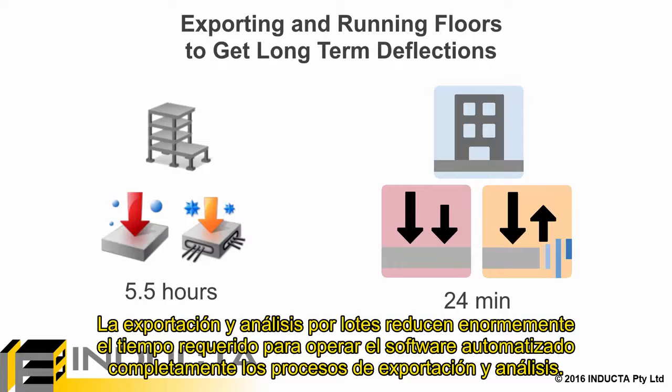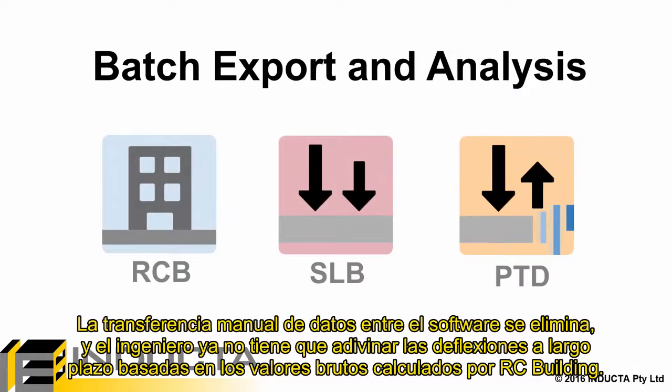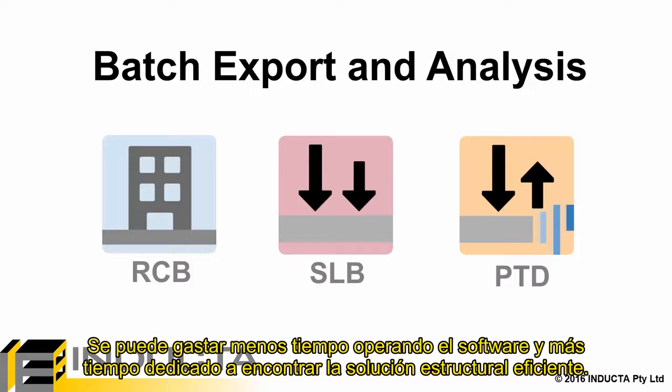The batch export and analysis greatly reduces the time spent operating the software by fully automating the exporting and analysis procedure. Manual transfer of data between the software is eliminated, and the engineer no longer has to guess long-term deflections based off I gross values calculated by RC Building. Less time can be spent operating the software, and more time spent finding an efficient structural solution.